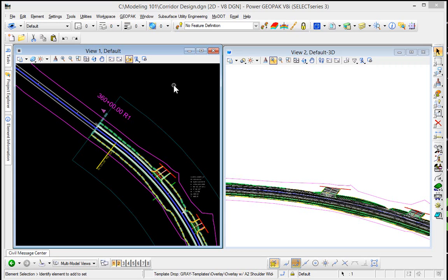One of the things I've seen done as best practice is they would have particular corridor files, say corridor section 1, 2, 3, 4, 5, etc. And then what they would do is take a blank file and reference each of those corridors into that blank file so that they could see all of them in one particular model. And that seems to work out very nicely, where your blank file is simply referencing in all the different corridor designs based on those particular station ranges. So that's another useful tip that will keep you from having to go in and process one 30-mile corridor versus just processing the area that you're working on at that time.